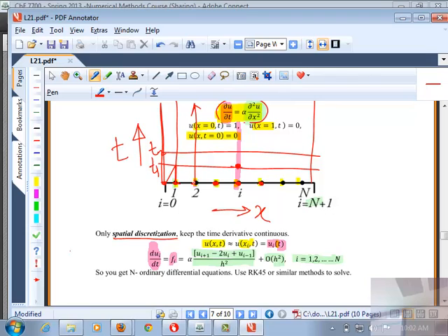What would be the final temperature? Do you remember from heat transfer, from the transport phenomena we did? When it reaches a steady state, what happens to the left-hand side? 0. So you get a second order differential equation. You integrate it twice, you will get a straight line. So the temperature profile is going to first go through in a nonlinear fashion, something like this maybe, as time increases, but eventually it will become a linear profile. And that's what this integration should give you: at every instant of time, what is the temperature profile across that length? So the initial condition comes from this.